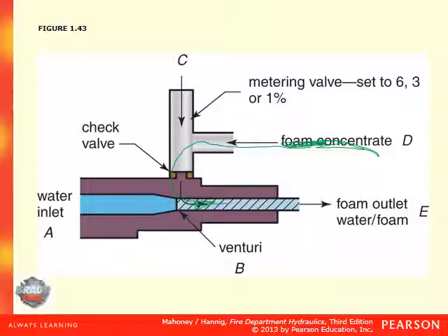And the reason that fluid will come out of that bucket into the line is Venturi, because the pressure coming in here gets siphoned down or knocked down into a smaller size outlet, creating a Venturi principle or a suction where this draws that fluid in. And then it gets all mixed around and, of course, out it goes.